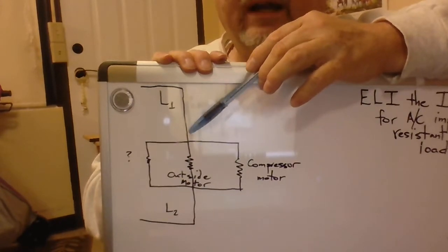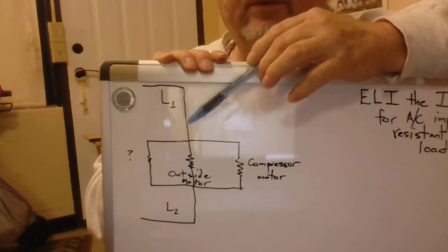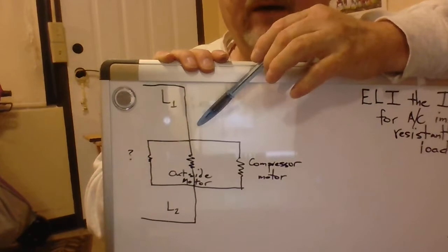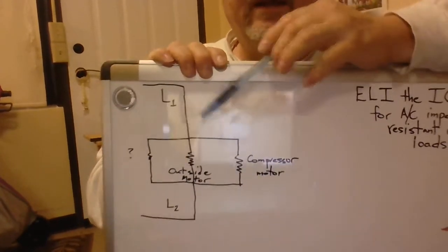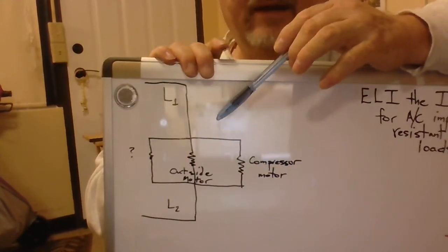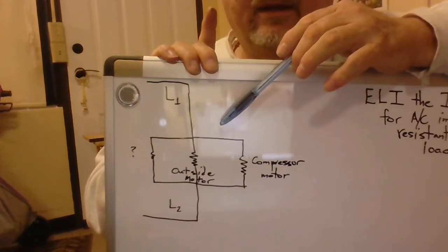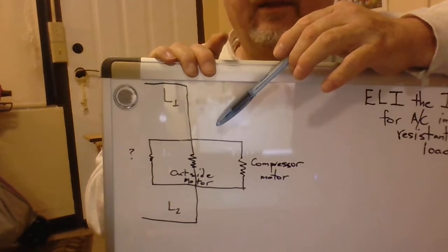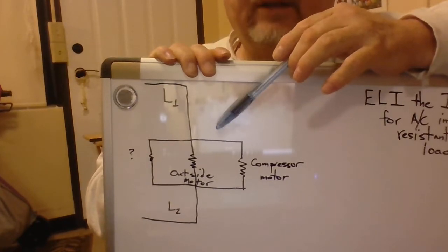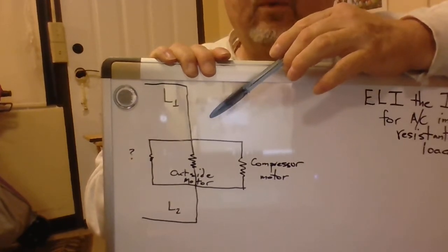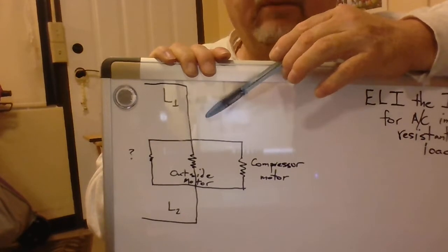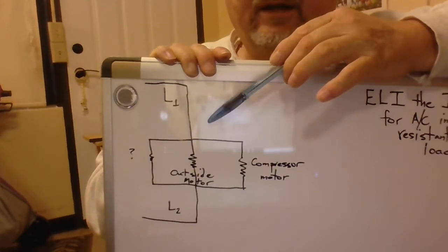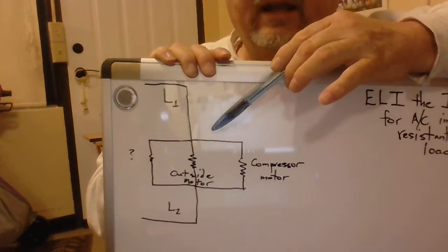You want to try and establish what the root cause of the problem is and take it from there. It's just like changing the capacitor, not changing the motor. You've got to get that on the ticket and explain to the customer that the capacitor most likely was damaged because the motor was causing a problem, whether it's a bearing failure coming or something along those lines.